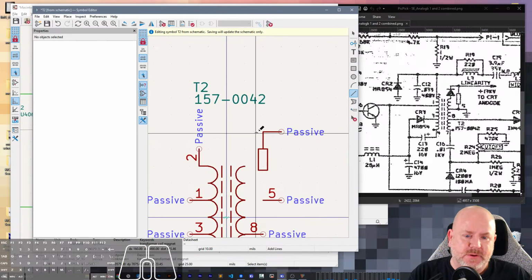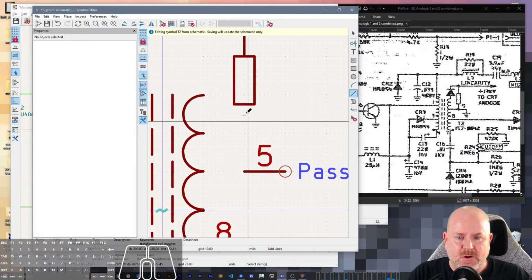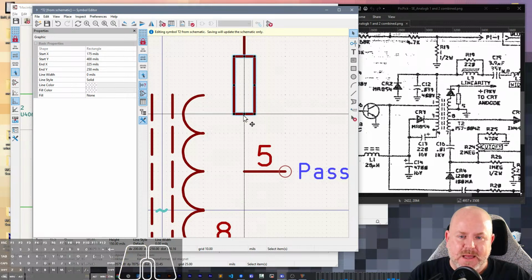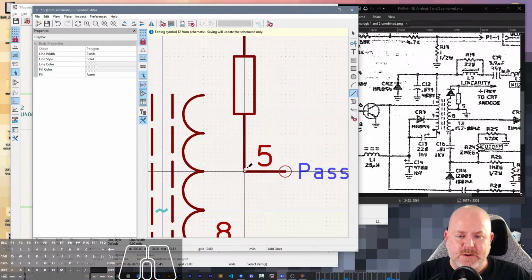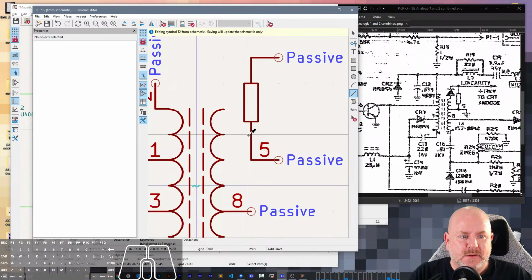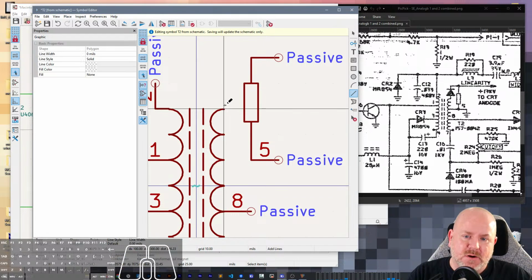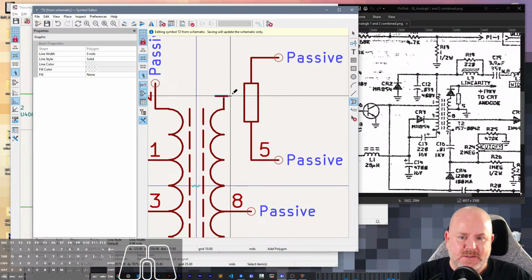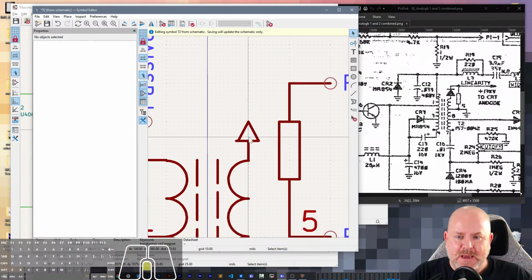So we took it apart on stream and figured out that a couple of the MOSFETs had gone bad and a few other things. We repaired it and it started working. Then another problem cropped up and I realized the voltage regulator it uses needs to be replaced. But I couldn't find the part in the package we needed.